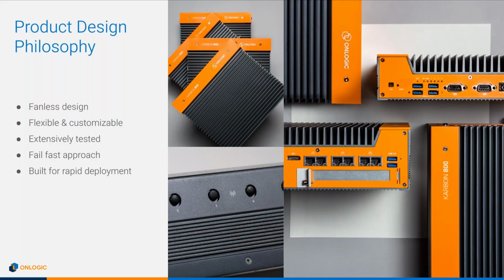So, how does this play into our product design philosophy? Well, as I mentioned earlier, anything in our industrial and rugged line is most likely going to be fanless. This means that we have to dissipate the heat generated by the computer with the shell of the computer itself. That's why you'll see large heat sinks on the top of a lot of our computers. These generally are going to be made of aluminum and are going to be used to get rid of any heat the computer is making.